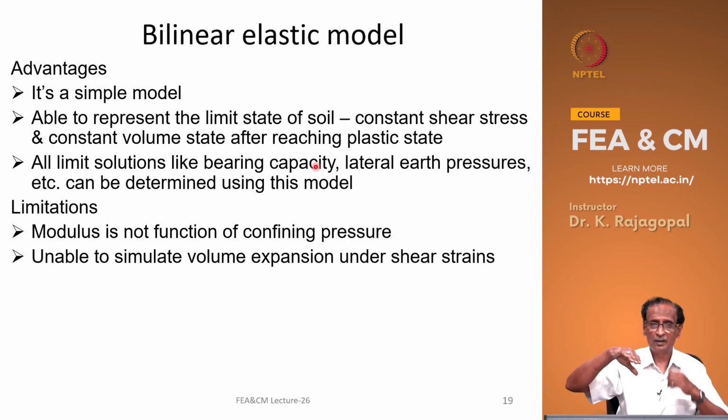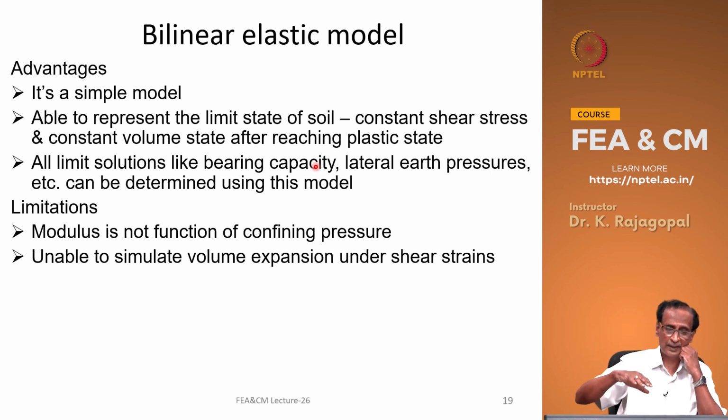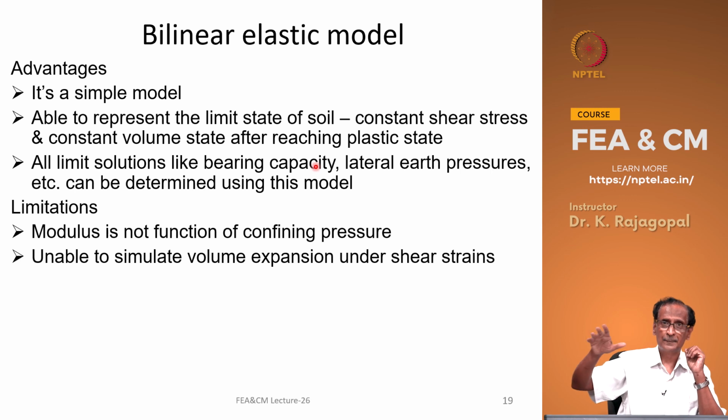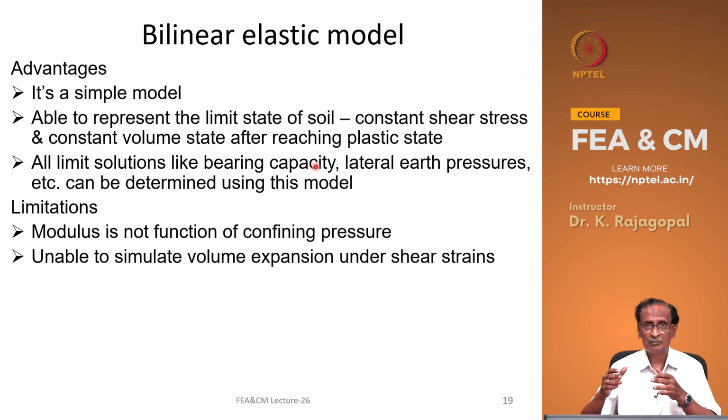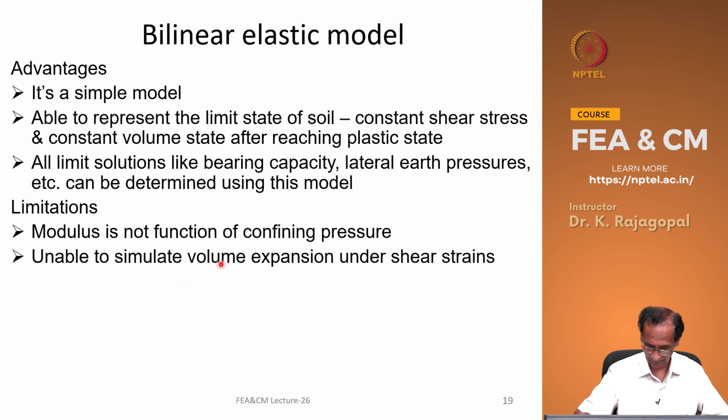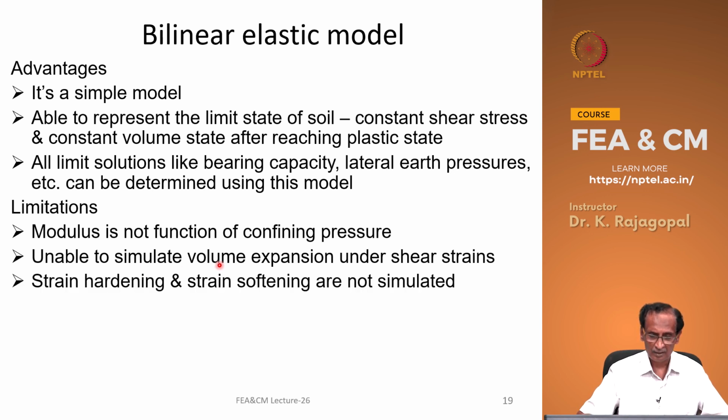But in our stress strain test, we see that the stress and strain are curvilinear graphs, not straight lines. And another limitation of this bilinear elastic model is we are not able to simulate volume expansion under the shear strains, and the strain hardening and strain softening are also not simulated.